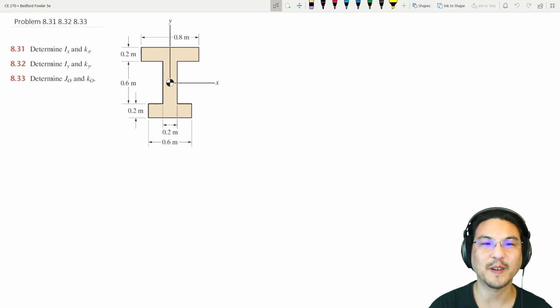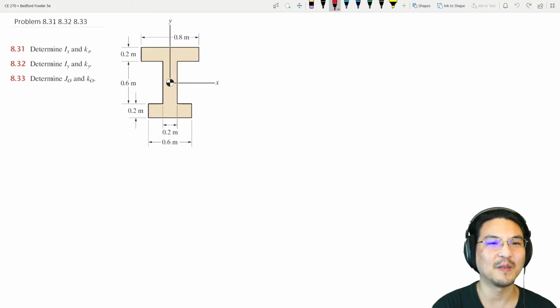Everybody, let's find the moments of inertia for this composite shape about axes going through its own centroid over here. So, strategy. We don't know the location of that centroid right now, so let's pick another set of coordinate axes that are convenient, and then we'll use the parallel axis theorem to move it over. So we could pick axes, let's say like over here, or here, or here, or here. It doesn't matter. There's no wrong choice.